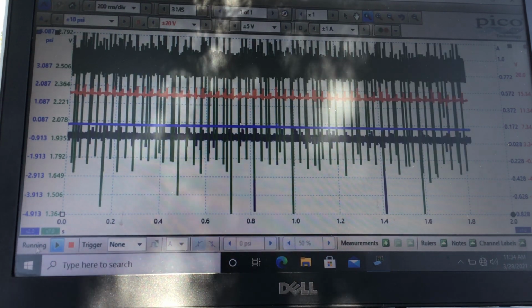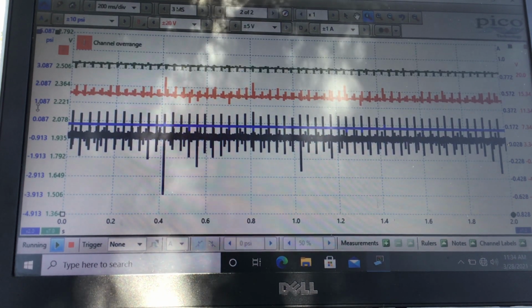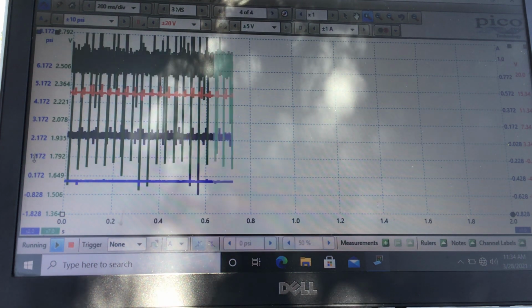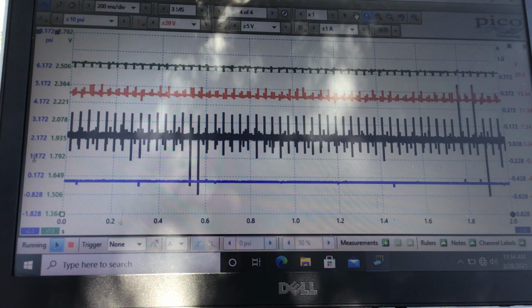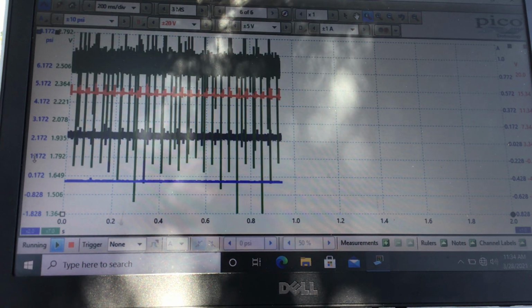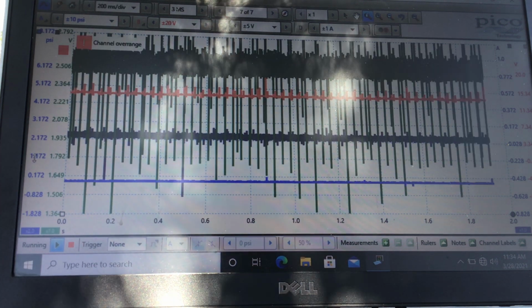We're running across the screen. As you can see, your 4 channels. I neglected to tell what they were. We're looking at A, B, C, and D. A is blue. That is our WPS 500 on range 2, keyed into the vacuum line in the canister on the evap side of the purge solenoid, not the intake manifold side.